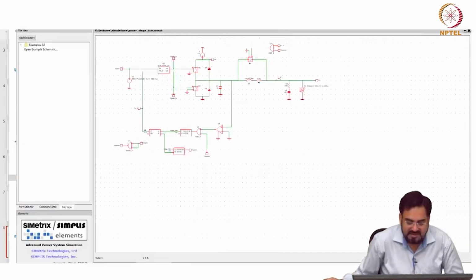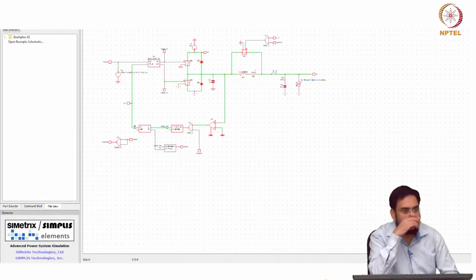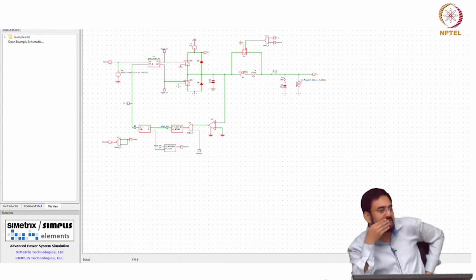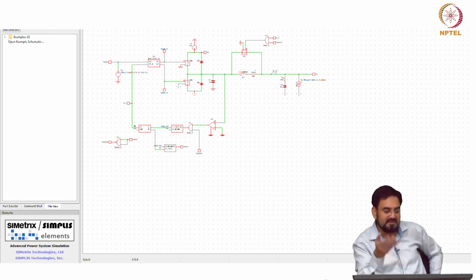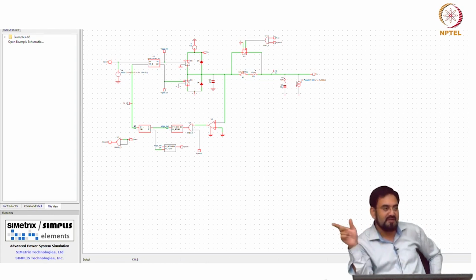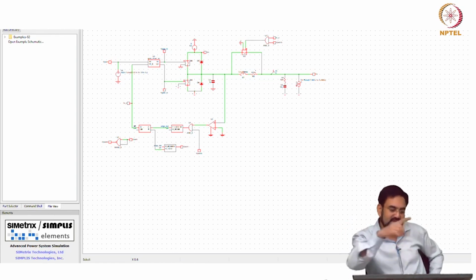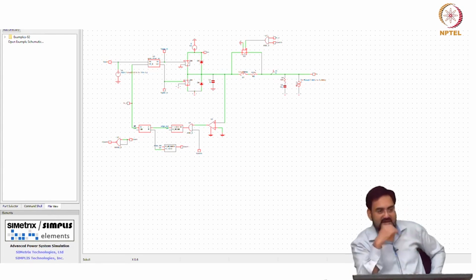Okay, but is there any drawback of having this? So, the benefit for noise sensitive applications is obviously very critical. I mean, it may cause EMI. It may cause even radiated EMI, because of ringing at high frequency, the antenna loop and all those, it may start radiating actually.